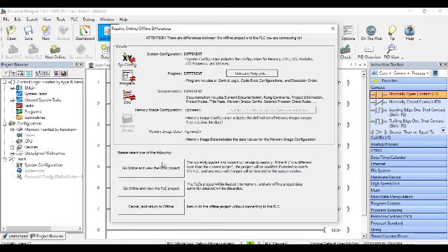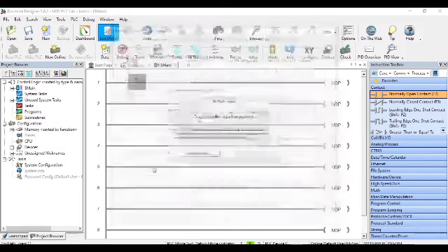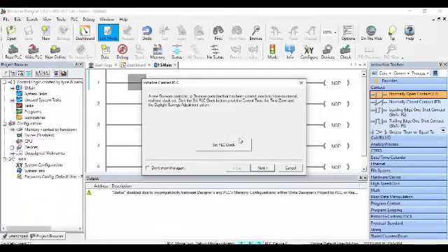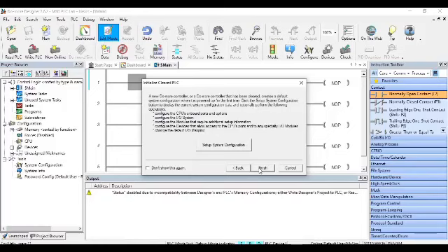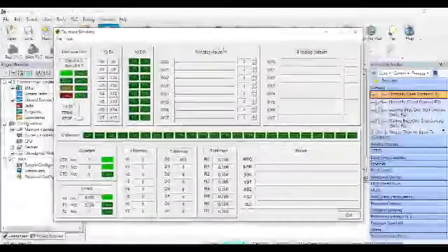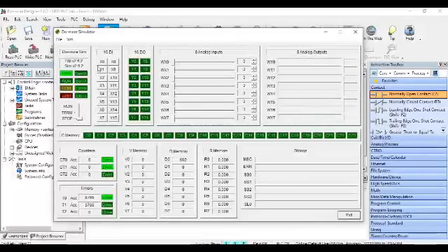So that's this one over here. Continue online, and this is not necessary, so we'll click next and finish. So if you did that, this PLC simulator should show up, and I can run this by clicking run, and I can stop this by dragging this slider to stop.